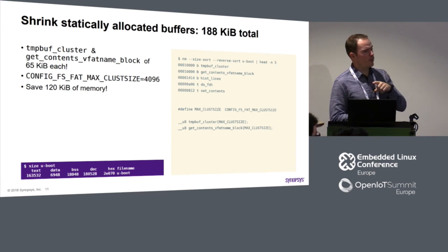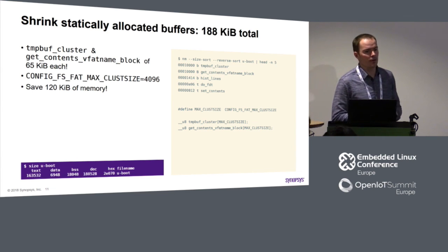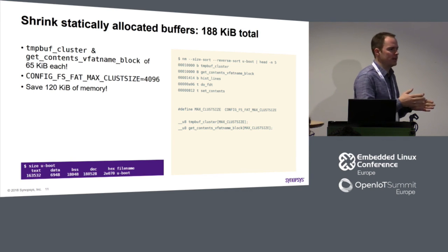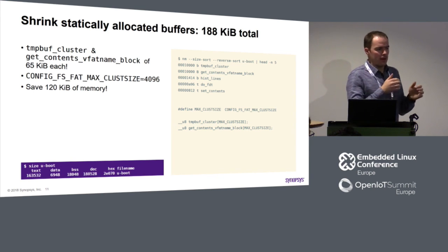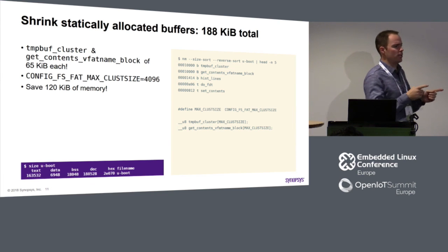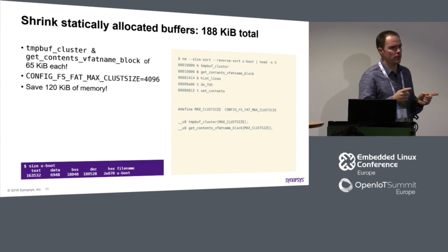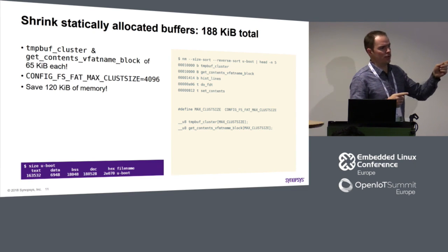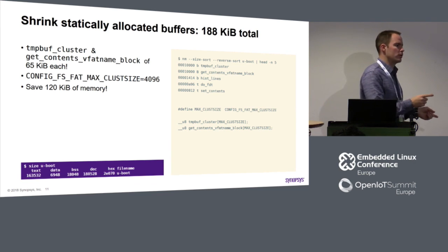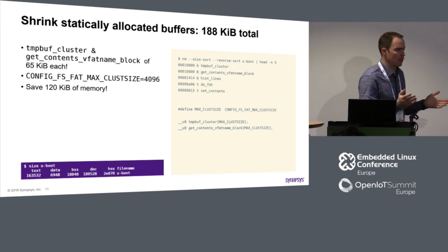And what Marek was saying is a practical thing, because you have a multi-stage boot. First, you have boot ROM, which actually does pretty much nothing. It might be a couple of lines of code which copy stuff, for example, from SPI word by word. Then you start execution from the first page, or, for example, as on x86, you have cache lines which you load, and you have 32 KB, no more.